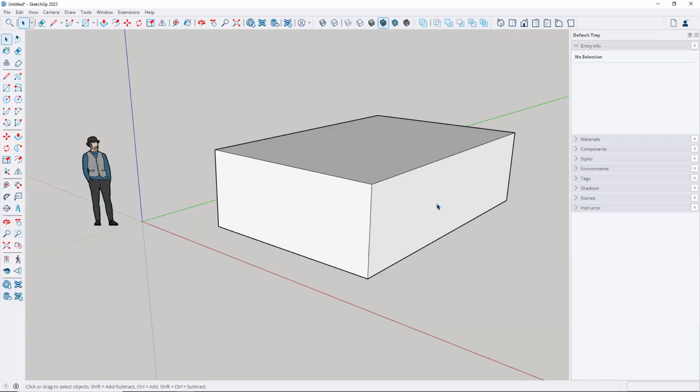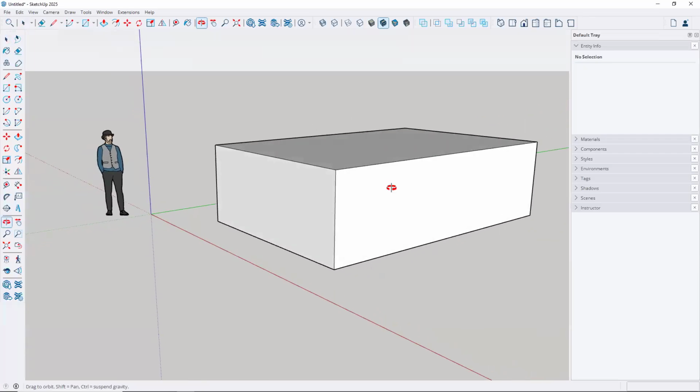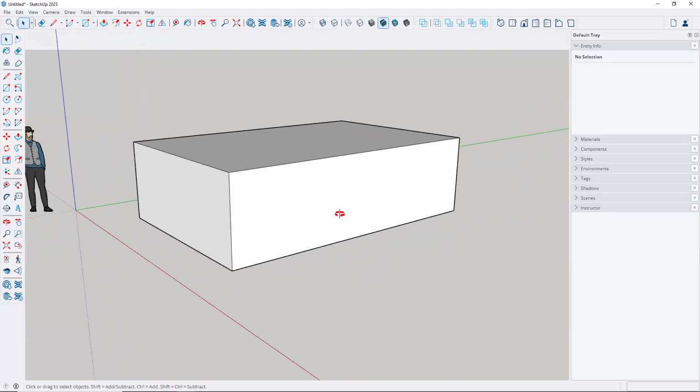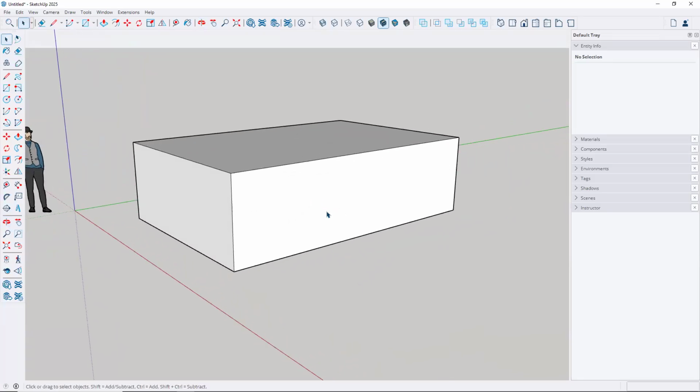All right. And then let's do this before we move on. I'm going to pan over like this. And I want you to see the nice thing about SketchUp here is I can type L, so I can start drawing a line. And then I'm just going to float it over here until it finds the midpoint.